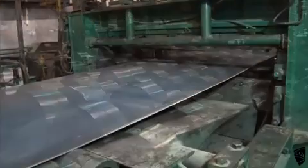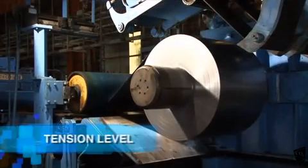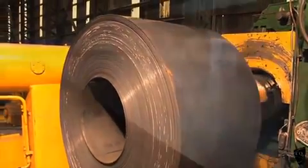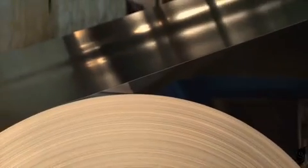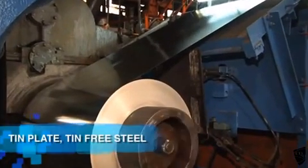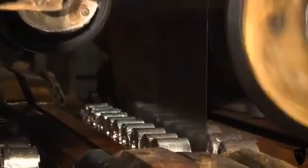In addition, AMSA has skin pass and tension leveling lines which improve the surface quality of the hot-rolled and cold-rolled coil, respectively. In these units, a greater thickness uniformity is achieved, which is an essential requirement for manufacturers in the automotive industry, home appliances, and electrical steel. Furthermore, AMSA produces tin plate and tin-free steel, which are steels produced primarily for manufacturing of metal containers. In both cases, the cold-rolled coil is subjected to an electrolyte bath with tin and chrome, respectively.